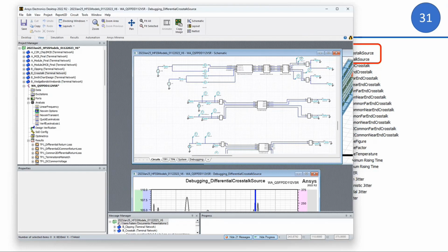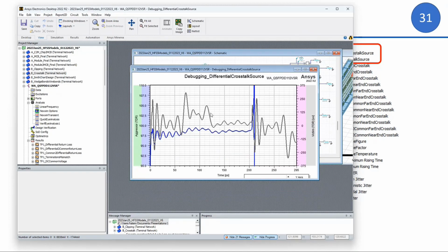You will be able to answer any question about crosstalk with 100% confidence, whether, as I said, during design or doing the measurements. Now, optimizing it, that's another thing. The only hint I want to give you here: when you optimize your crosstalk, if you try to optimize the big one and it didn't work because you ran out of options because of the dimensions, please go after the small ones. You will be surprised. Maybe sometimes suppressing the small ones will make you pass the spec. That's the advice I wanted to mention.